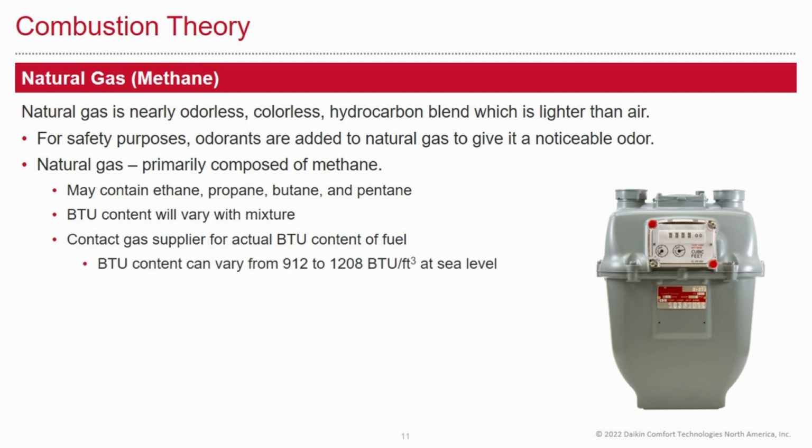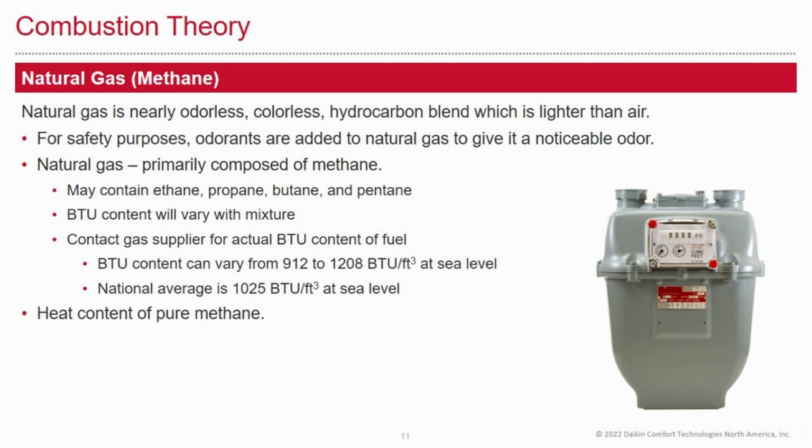BTU content can vary between 912 to 1,208 BTUs per cubic foot at sea level. The national average is 1,025 BTUs per cubic foot at sea level. Heat content of pure methane, 1,011 BTUs per cubic foot at sea level. That's 23,811 BTUs per pound.